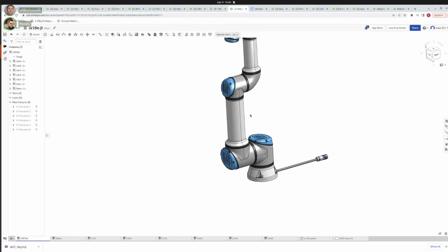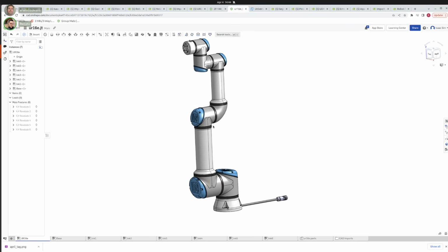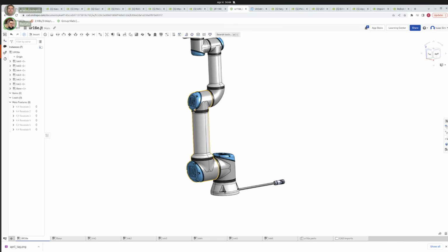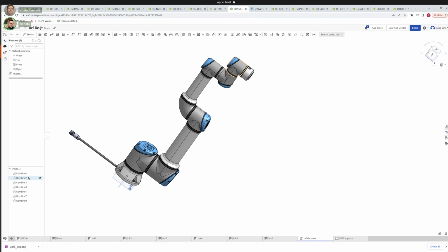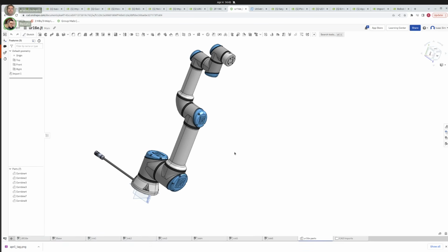Here, what we expect now is that whenever this robot is imported, all the components should come as their own rigid bodies with the properties that we can collect from Onshape. One thing I wanted to make sure of here is that we can already come with some predefined inertia matrices computed, but we need to go item by item and assign some material to it.